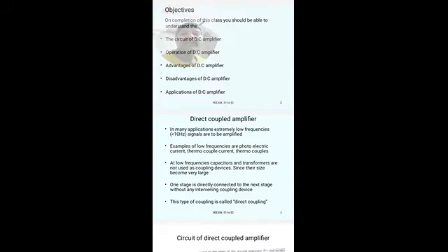To amplify signals with very low frequencies, the capacitor coupled amplifier, the RC coupled amplifier, is not suitable because it offers very high reactance to low frequency signals.